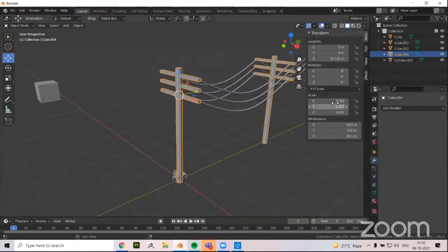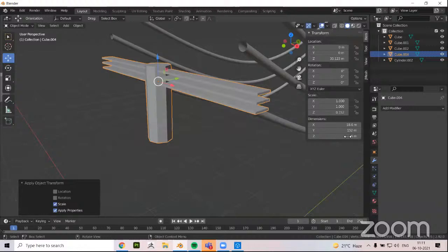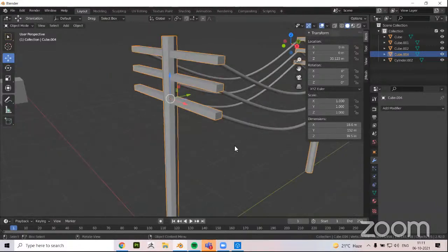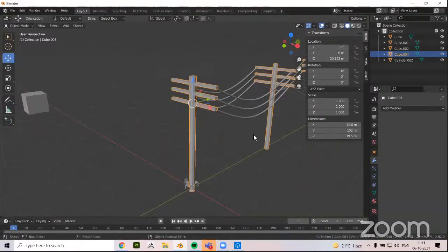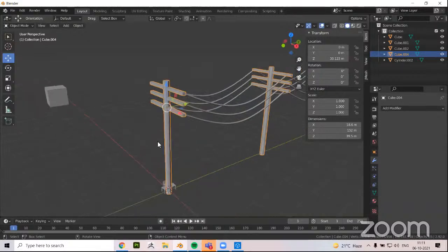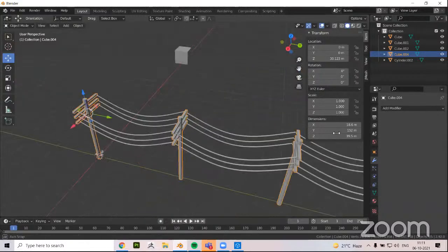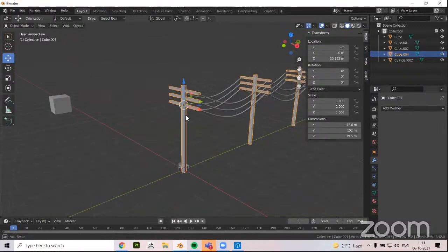Okay, wait, sorry, it's scale, right? In the dimensions part, sorry, not the location, in the dimensions part, I'll make sure in Z it's 6 meters in height, then it will be this much smaller, because right now it's around 39.5 meters. But once we have an actual input done, I'll just give that input. And once I hit export, this thing says it's 39 meters in height. So if I bring it into any different 3D software, it will be 39 meters in height in that software as well. Unless we can always change the scaling in any software we have.